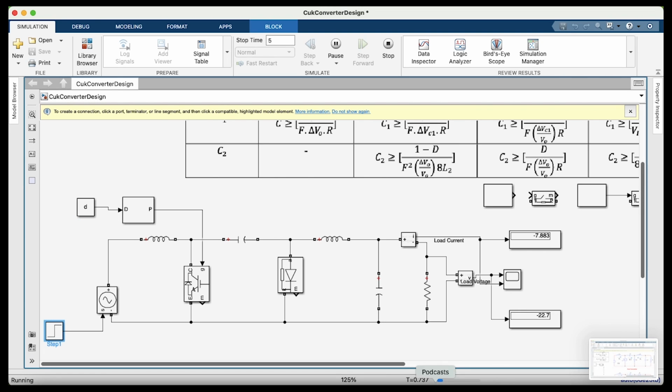Therefore, in order to introduce a PID controller, this constant duty cycle will be removed. So look at exactly one time period. Now the duty cycle is near 1. After that, look here, the output voltage is slightly increased to minus 28, and also look at the current. This happens due to the slight change on the input side, so this will affect the constant output voltage.